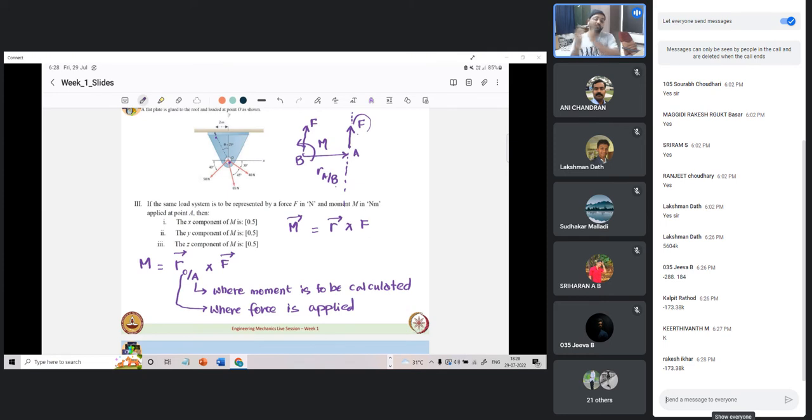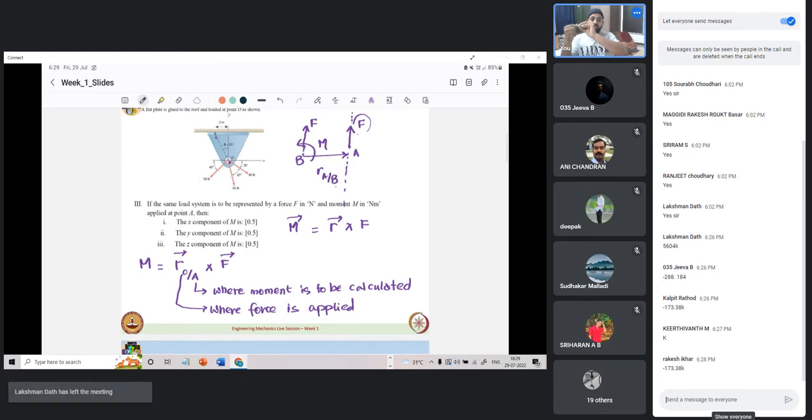Now we want to shift this force to some place else, not just shift. The constraint here is that it should have exactly the same external effects. That is why we go for resolving the force into an equivalent force and a couple. As you see on the screen, from point A, if I want to shift it to point B, as someone had also asked, first we will take this force at A. Shift it to B. Again apply another negative force at B because initially at B there was no force. This negative force and the applied force create a couple.